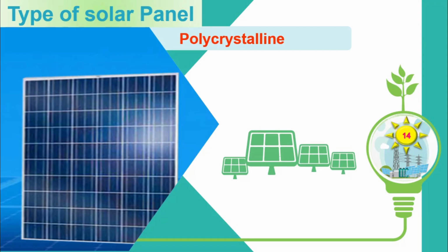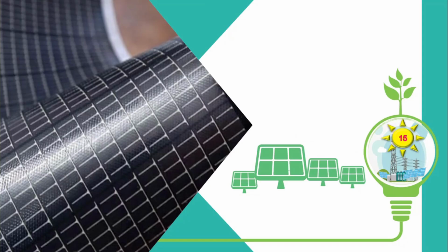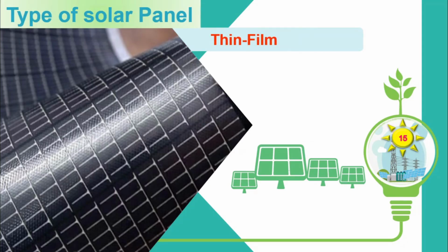Better for cloudy climates, polycrystalline panels are easier to make than monocrystalline ones as they are made from multiple silicon crystals. Their non-uniformity hinders electron flow, resulting in lower energy output. And they have lower efficiency compared to monocrystalline panels. Their appearance is characterized by a blue color close to navy. These panels have a very suitable temperature coefficient, which is why they are recommended for environments with very high temperatures.